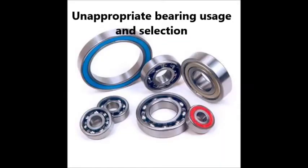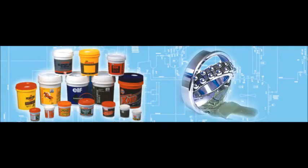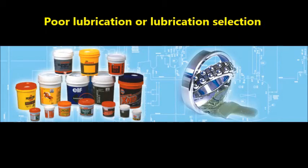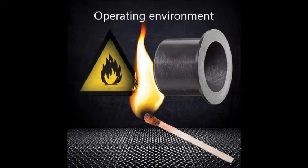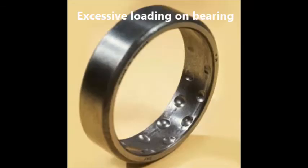The following causes should be considered: inappropriate use of bearing, faulty installation or improper processing, improper lubrication method or sealing device, inappropriate speed and operating temperature, contamination by foreign matter during installation, or abnormally heavy loads.